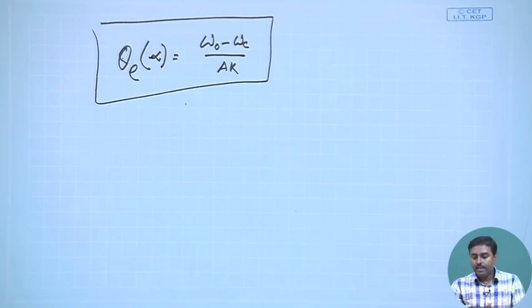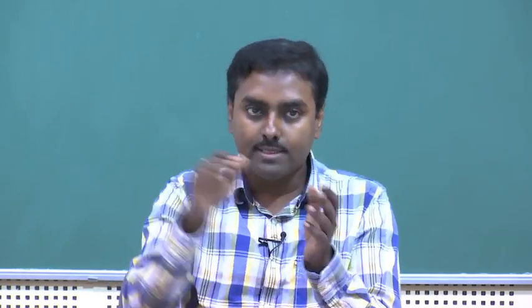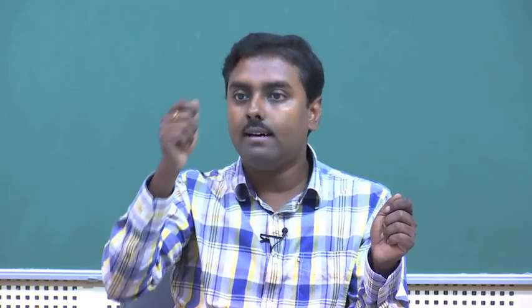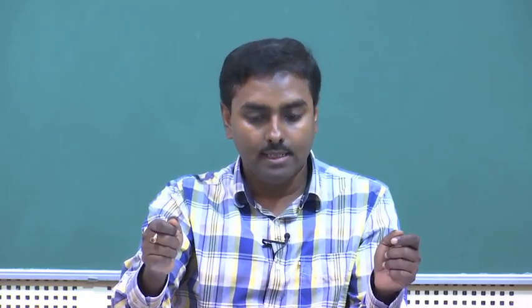So, what has happened? I have put a first order low pass filter, because Hs was 1 within the band of interest, and after that it must be a low pass filter. Whenever I put that first order characteristic, or within the band all pass characteristic, this should be the final phase error. There was an input frequency error: we have omega 0 and the free running frequency was omega c. It can actually track that frequency, there was no problem in that.